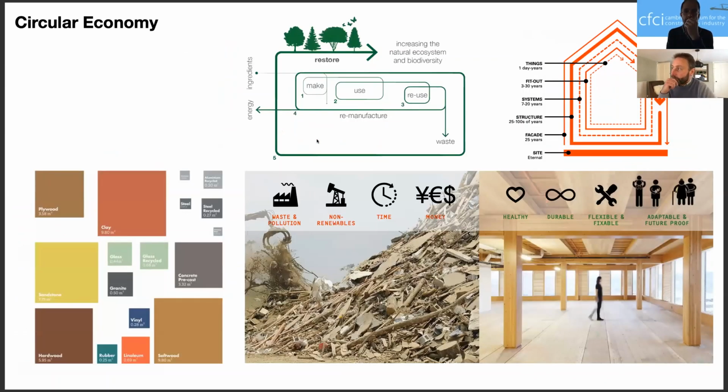So first of all, what can we build with? The first thing with modular in particular is understanding that every component within a modular building will have a different lifespan. That's whether it's the structure itself, which might last 100 years plus, all the way down to the fit out. And how you design this in to enable change of these layers at different times during the lifetime of the building without producing waste.